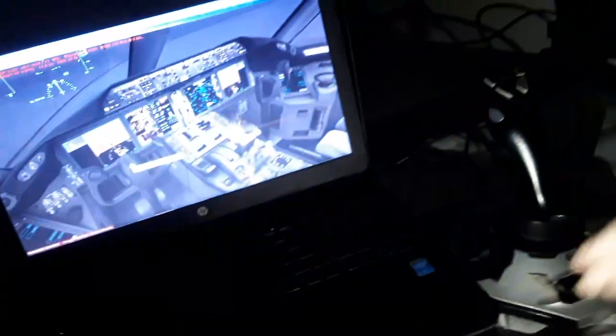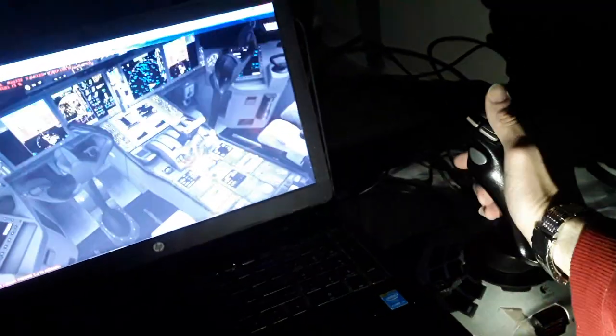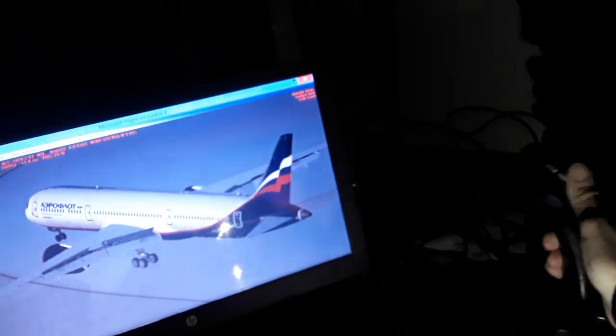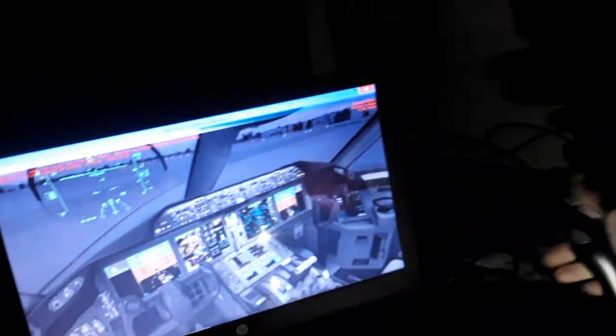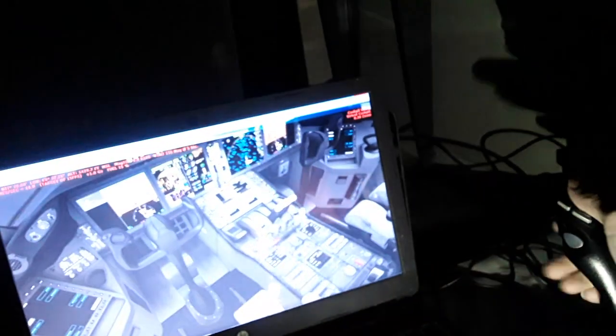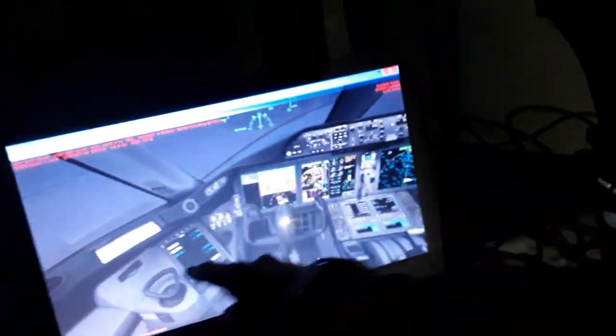So you can see here all the flight controls. We move around and utilize the elevator, landing gear external retract, the rudder, elevator, spoilers, ailerons, flaps, speed brakes. So we need the landing gear external retract, parking brakes, thrust reverser for the engine, flaps and slats, tiller, nose wheel steering. So we need hydraulic fluid over here, pressurization from the pumps: we have the engine driven and the electric driven, and also pressurization from the engine and APU, as I told you.